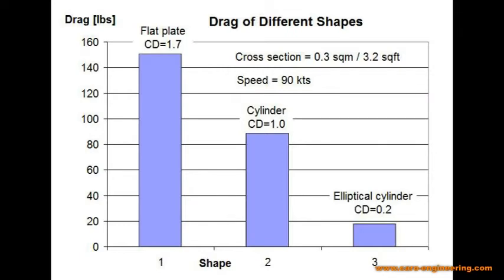The drag coefficient CD of simple shapes can be looked up in tables. For more complicated or optimized shapes like fuselages or airfoils, it is calculated with aerodynamic programs or measured in wind tunnels. Make sure you use the correct cross-section. For fuselages and similar objects, the drag coefficient is referenced to the frontal area, while for airfoils and wings, the drag coefficient is referenced to the chord or wing area.